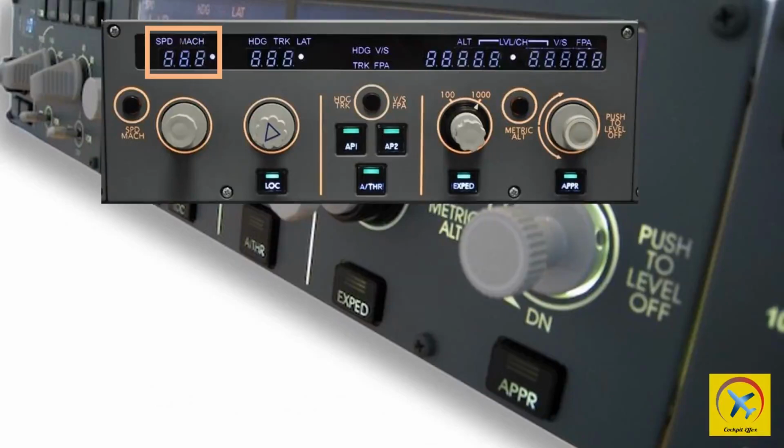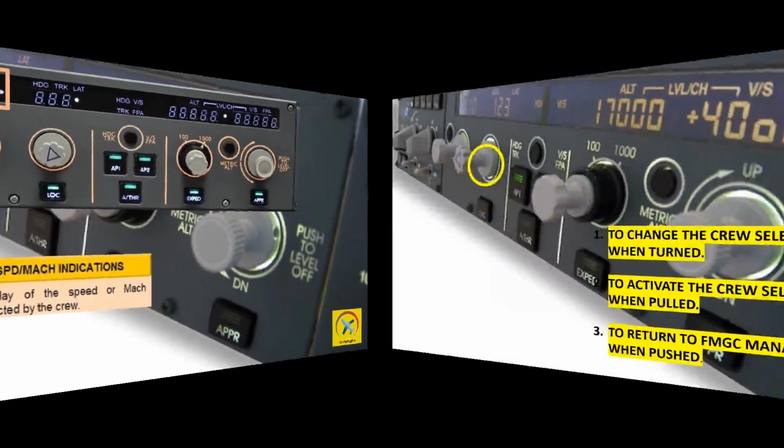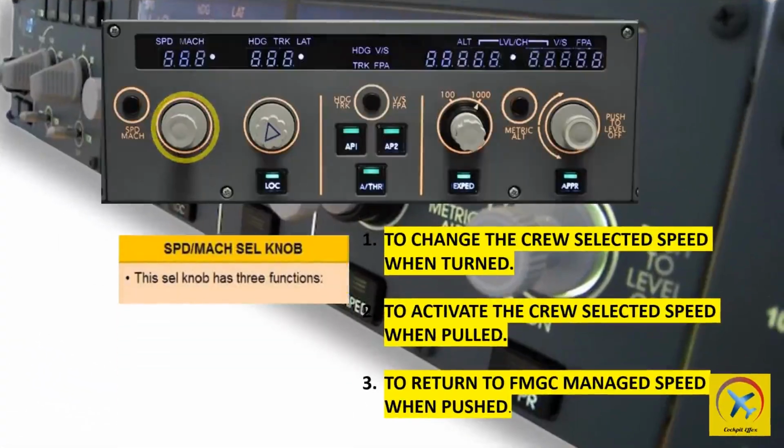The speed or Mach number selector when rotated, changes the value displayed in the speed or Mach number window. When pulled, the selected speed displayed in the speed or Mach number window engages. If the selector is pulled when the speed or Mach number window contains dashes, the window displays the current airspeed. When pushed, FMGS managed speed engages, the managed speed light illuminates, and dashes appear in the speed or Mach number window.